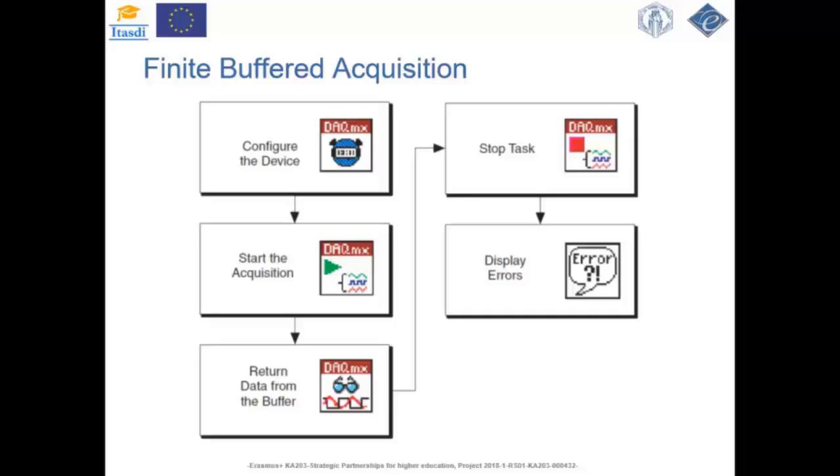And in order to have really precise measurements carried out here, we can use this technique, which allows us to acquire a certain amount of samples at equidistant time intervals, controlled by the hardware clock of the device, rather than having the timing being controlled from the software.